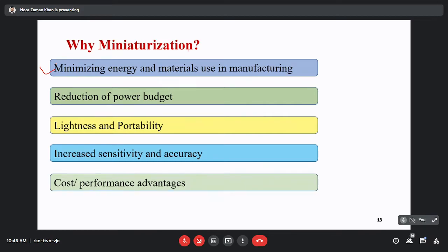I'm giving you an example. Suppose you want to reduce the diameter of a rod from 100 mm diameter to 80 mm diameter, then what will happen? 20 mm material will be removed. 100 mm to 80 mm diameter. So here we need to remove 20 mm material. However, depth of cut will be 10 mm, but we'll remove 20 mm material, and this will be scrap. So in this case, the scrap material is large.